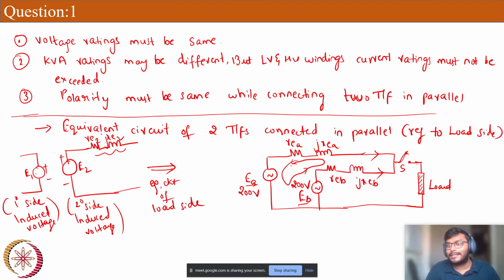That's the condition which we don't desire, because we expect those two voltages to be the same in magnitude. But when this kind of mismatch happens, a no load current will flow among them, which we call a circulating current. So that's what happens when any voltage mismatch happens.